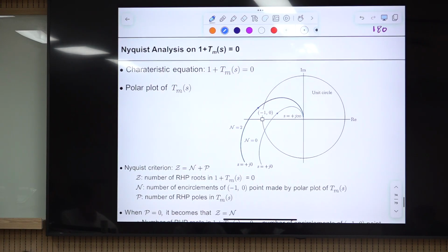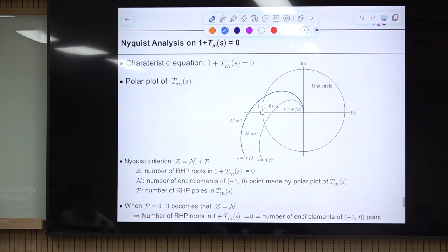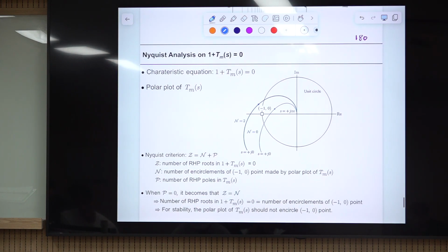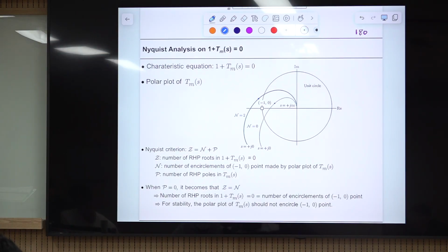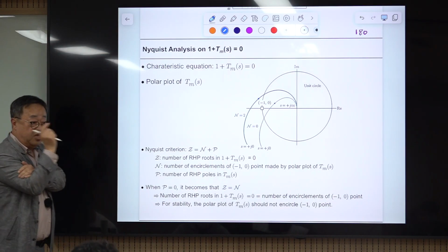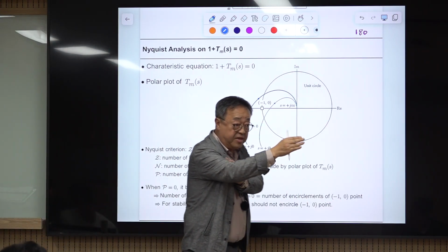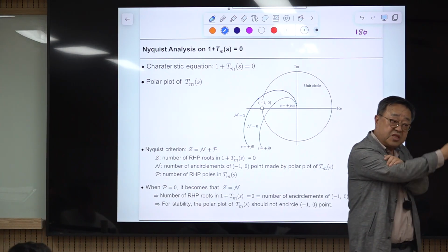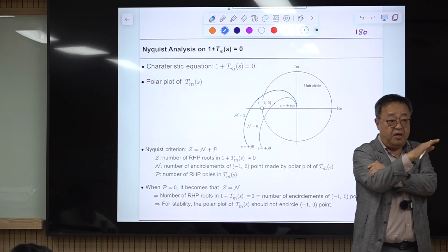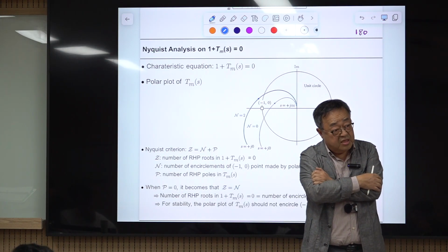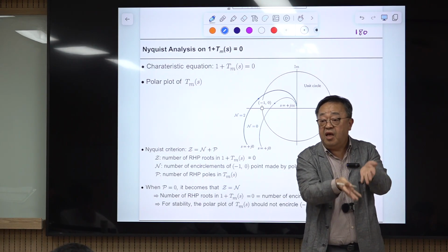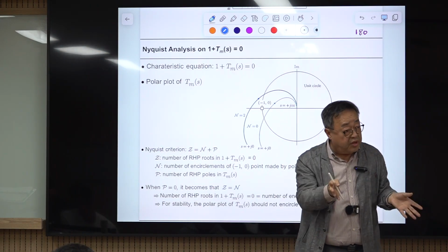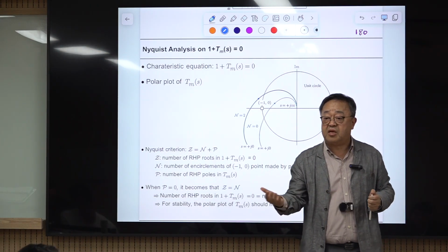And this is one very important topic. We discussed the stability using something else. We defined the stability using this sinusoidal input injected in the feedback path, and we discussed the returned signal. We analyzed the phase of minus 180 degrees and the ratio between the injected signal and the measured signal, and somehow with that you can establish some stability criterion.